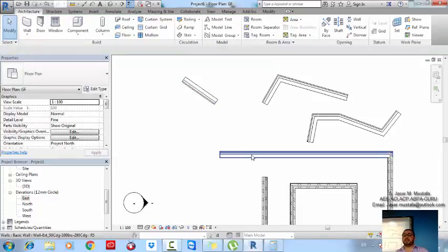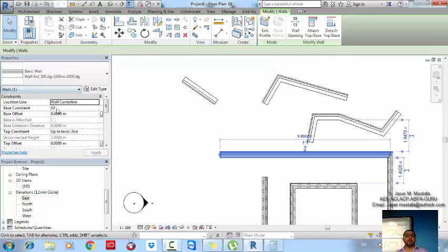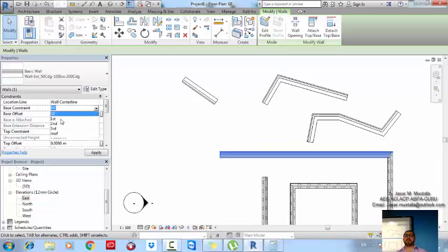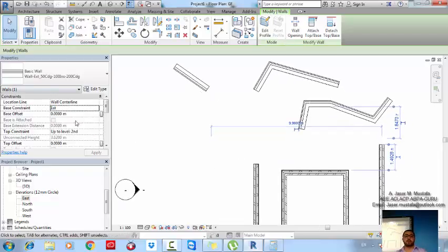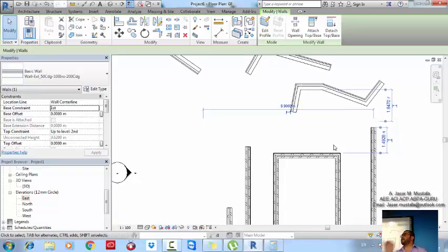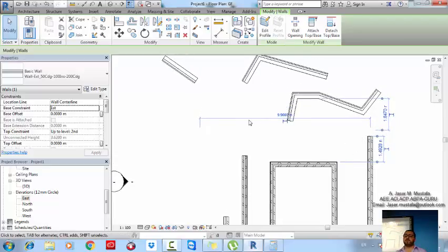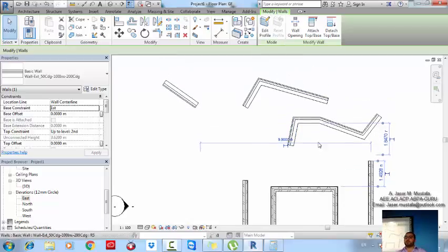Now, once I select this wall and change the options in the properties palette, for example, I don't want it from the ground floor, I want it from the first floor, it will change the constraints or the option on the selected object only, on this wall only. If you see now, I can't view the object because it's above the ground floor plan, but I can see 1, 2, 3 and go on. Why? Because I have just changed a selected object's option.